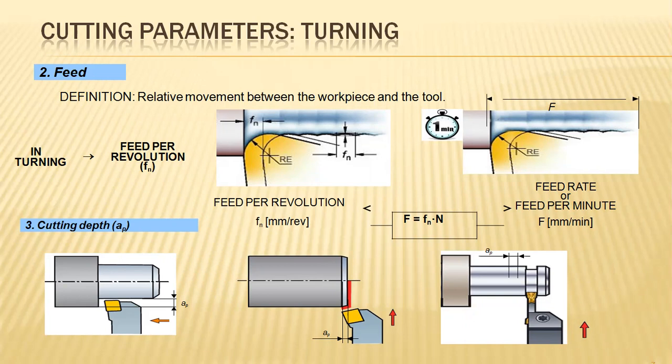Considering a turning process, normally we have to analyze how much feed per revolution will be consumed by the tool, and how much depth is needed for removing the material, either it may be 1 mm, 2 mm, 3 mm, or 4 mm. That will be identified.